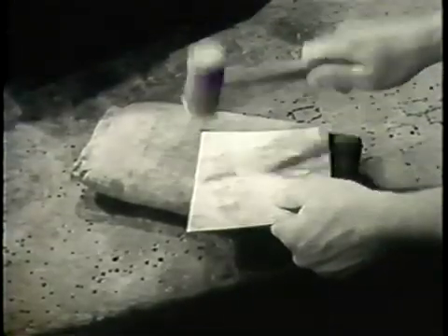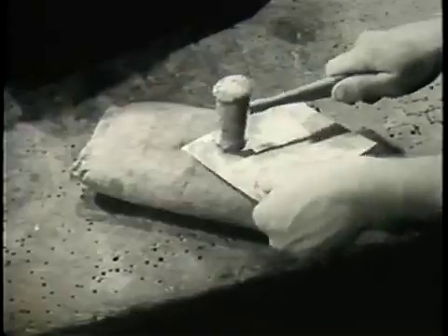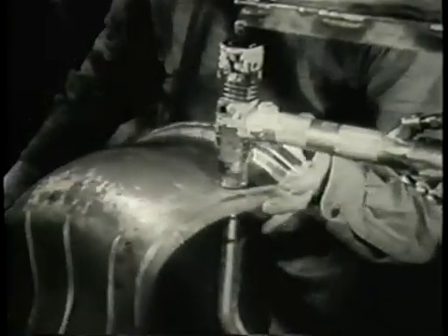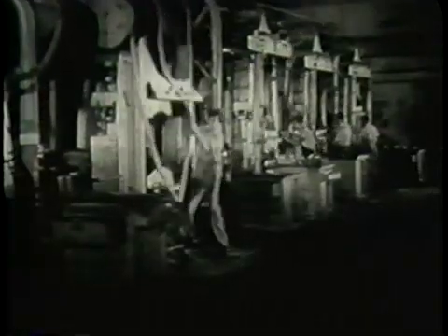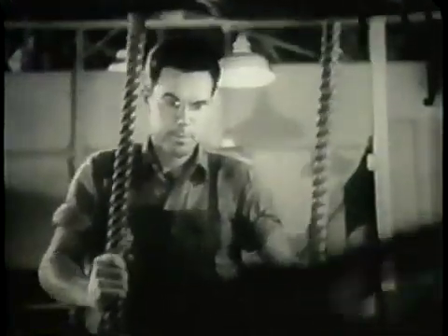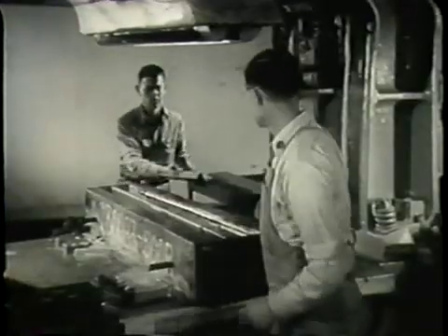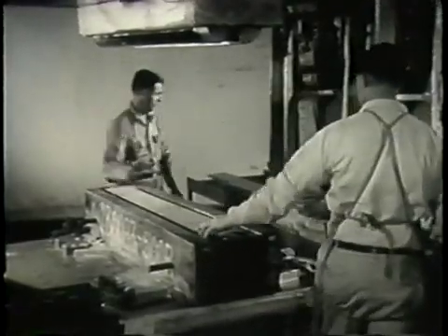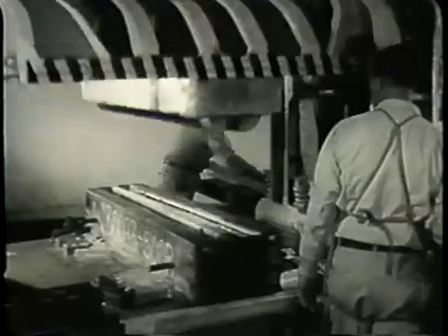Hammering is another forming method that may be done either by hand or with the use of automatic devices. The process of drop hammering, capable of handling large parts and forming severe shapes with compound curvatures, may be performed with a rope-operated hammer or a pneumatic hammer. Hydraulic hammers are also used, but less extensively than either of the other two types. A desired part may be formed by a single blow of the hammer, the alloy sheet being shaped by pressure between the mated punch and die.